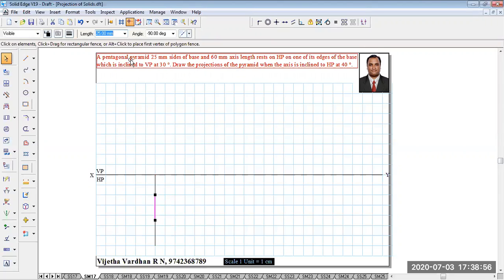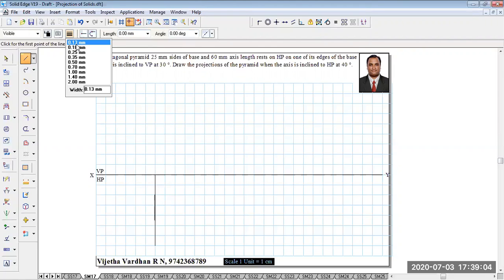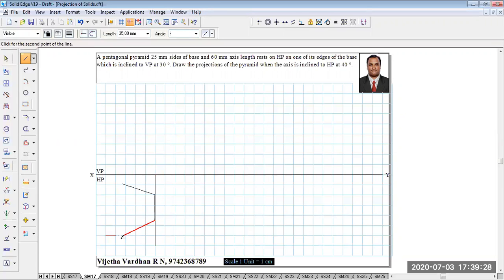Since we have to construct the side resting pentagon, I'm going to start like this. Now, to construct the pentagonal edges, let me show you the procedure. You have to follow it. What you are supposed to do is keep your protractor at this corner and then measure 72 degree as the exterior angle, and draw a constructional line like this. And then keep the protractor at this position again, and again measure 72 degree as the exterior angle.